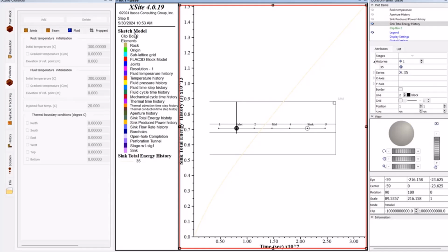We can represent anisotropy actually in two ways. We can represent it as a matrix anisotropy, where the properties of the springs are a function of their orientation. But there's also a way to represent anisotropy by explicitly putting in discontinuities, depending again on the spacing.